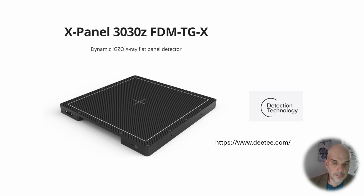And this is an example detector for X-ray imaging systems, a flat panel detector from Detection Technology. It's a 3000 by 3000 detector array, 30 centimeters on the side with 99 micron pixels. So why did they choose to do this? What makes it so that one would choose to have 99 micron pixels? That's the key issue in figuring out the resolution of the imaging system.